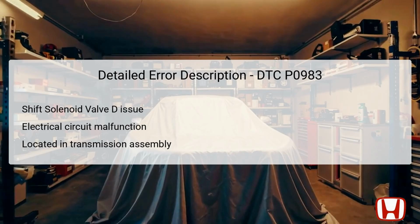The solenoid is housed within the transmission assembly, positioned so that it can effectively manage fluid dynamics during gear shifts. An open circuit in this solenoid means there is a break or fault in the electrical pathway that can prevent it from operating correctly. Identifying this issue requires thorough electrical diagnostics, as it is essential to verify whether the problem is indeed an electrical circuit failure or a potential intermittent issue with the vehicle's electronic components.